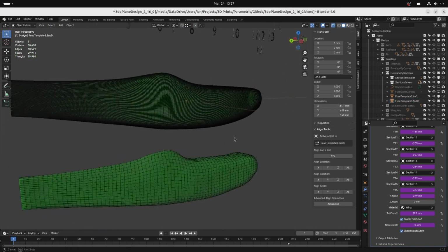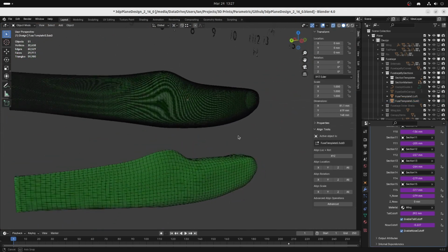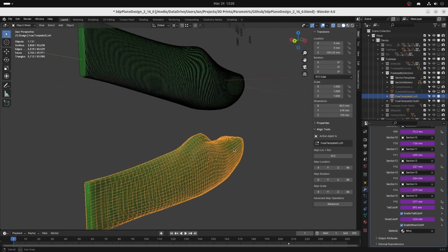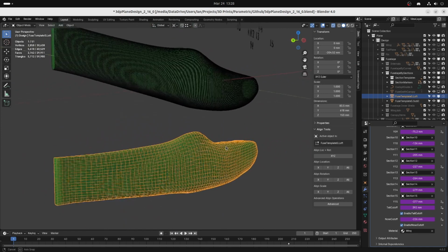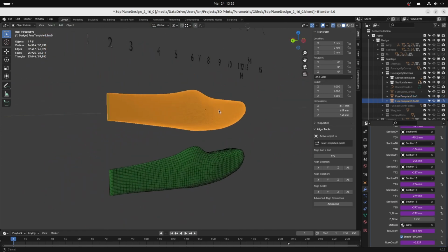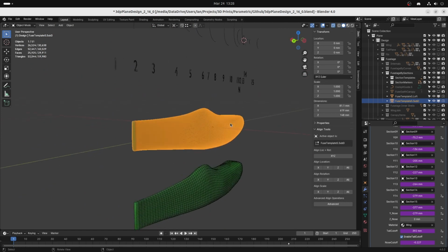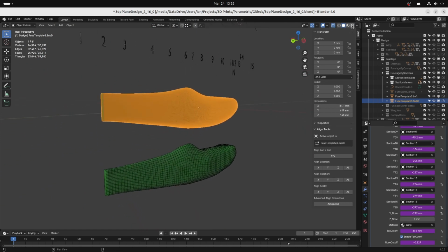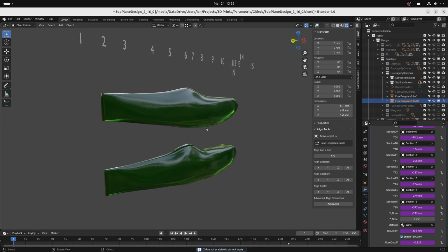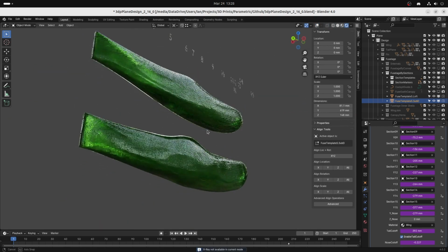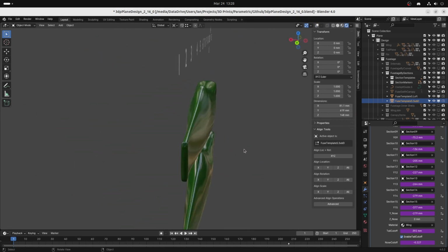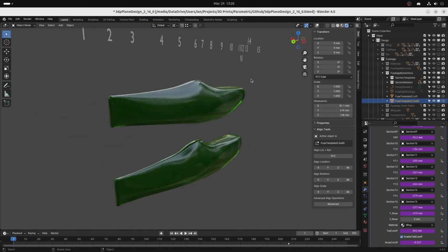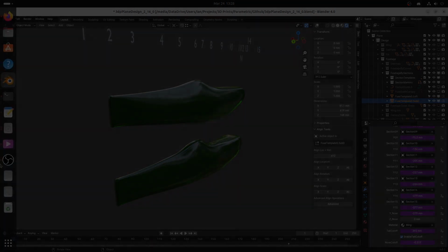So in summary, both versions are still useful, depending on your requirements. The Loft version fits exactly to the provided sections, so you have to take care that these are accurate and they don't change too abruptly. The Sub-D version tends to give you a smoother result, but at the expense of dimensional accuracy. If I choose a reflective material and we look carefully at the two objects, it allows us to see the small differences between the two modelling techniques. I guess simply choose the one that you like the best.